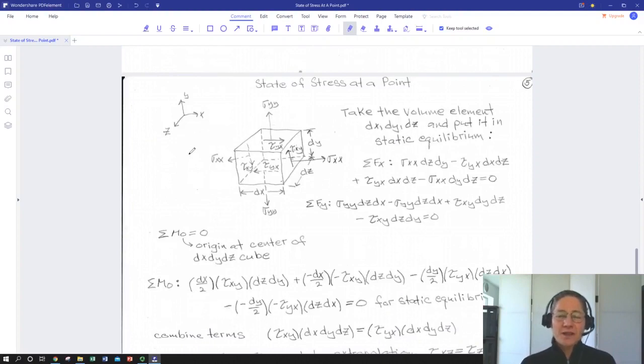Plane stress conditions also make it a little bit easier to define certain relationships. So when we start looking at elasticity and relating stress and strain, we might start with a plane stress or plane strain condition to do our derivation, with the understanding that this would apply even if we added the other orthogonal directions to it. But in practice, there are those thin sections and surfaces that are by their very nature always in plane stress.